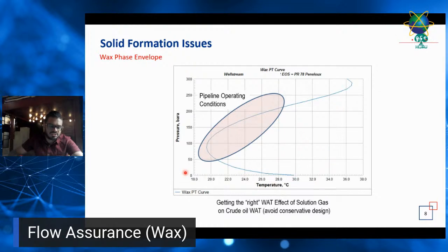However, we may need to check on asphaltenes. If we mix gas and oil, asphaltene can be an issue, because that's when asphaltene will start to destabilize and precipitate. Unlike wax, which is a reversible process, whereby we can at least melt it and recover the oil, asphaltene, once it's formed, will stay in your production flow line and also in your separators.